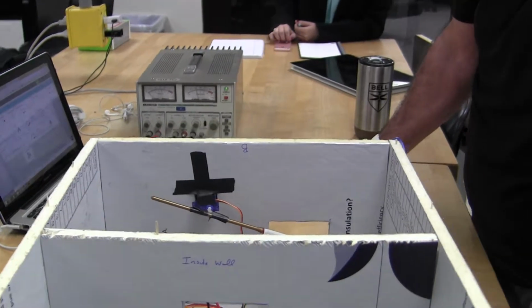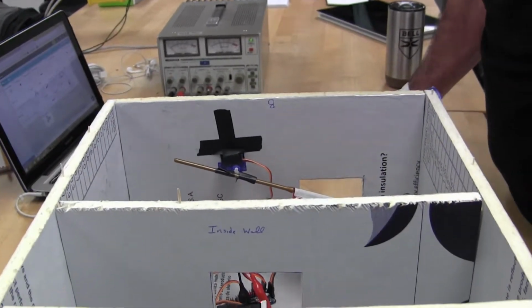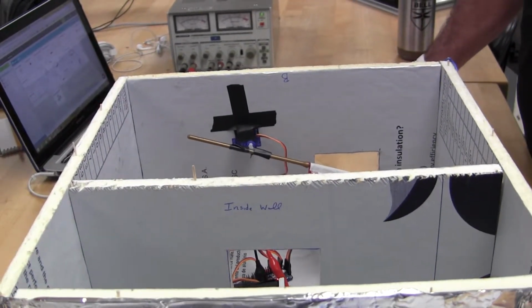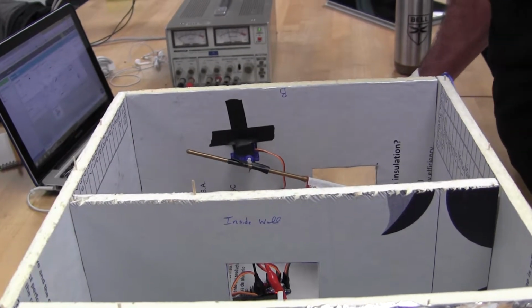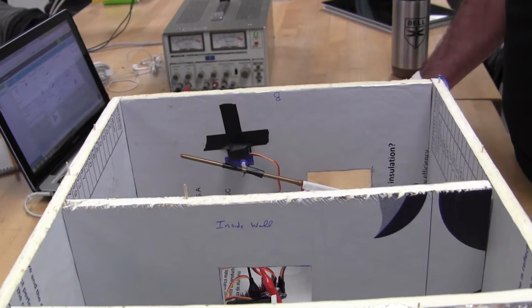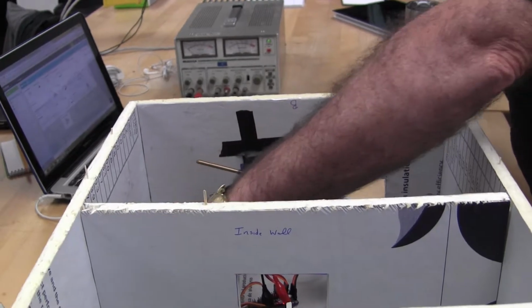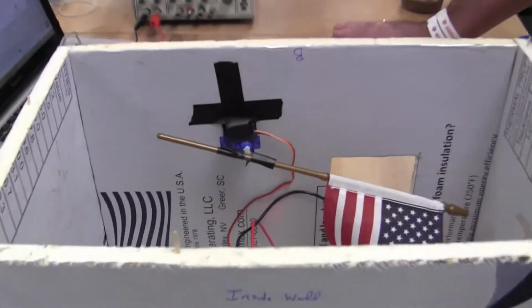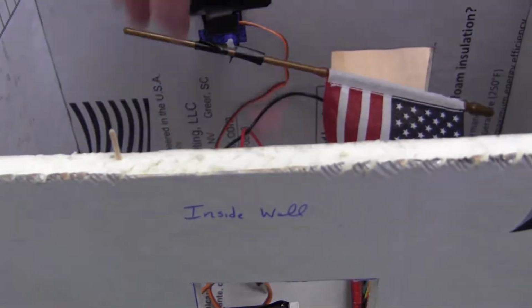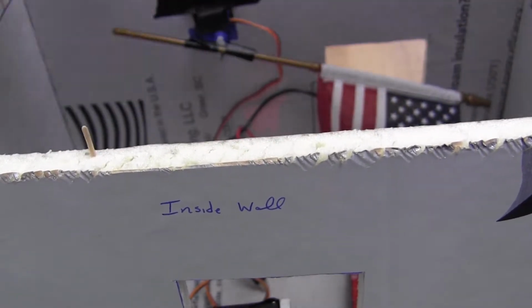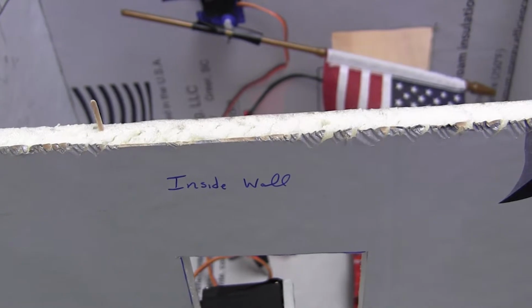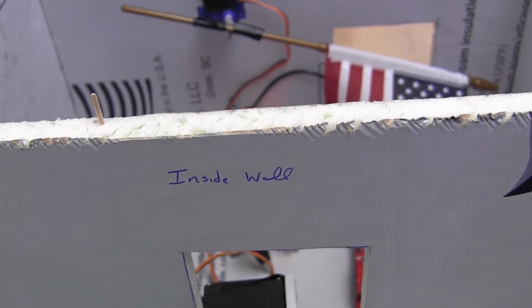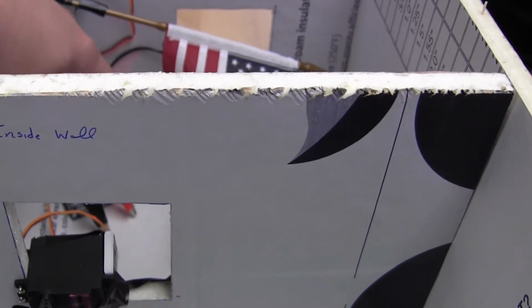Maybe I'm not making myself clear. You have a control signal that you're sending, but you're also sending power and ground, right? Yes. So how much power can I control off of this board? Could I put a 5 amp servo over there and still control it? Not with the onboard power regulation on this board.